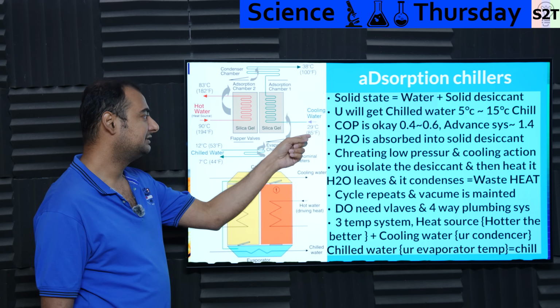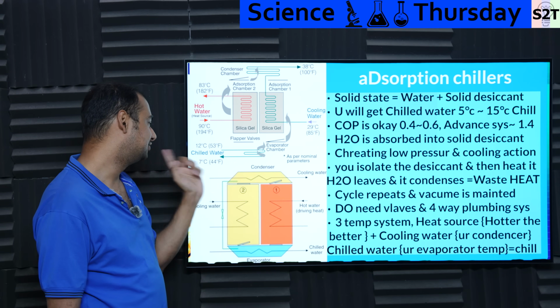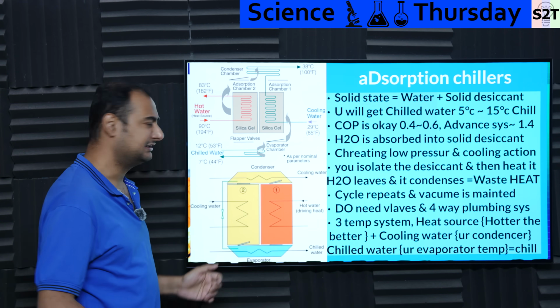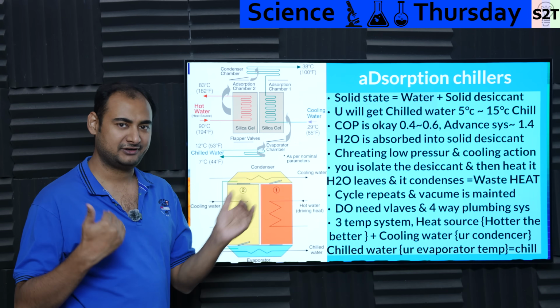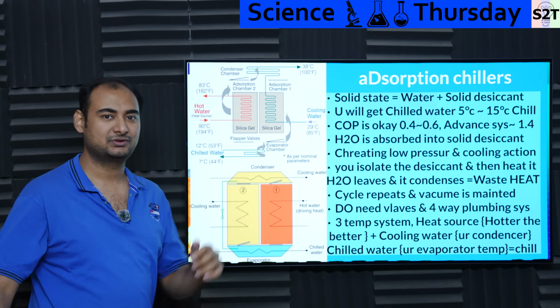So in this design, this is 90 degrees Celsius, water goes in, 83 degrees Celsius comes out. Cooling tower water is 30 degrees Celsius, 38 degrees goes out. The chilled water is 12 degrees Celsius to 7 degrees Celsius, more than decent enough. And again, that's what I'm thinking, what if I fine tune the system so this water goes up, as in like 15 to 20 degrees Celsius.